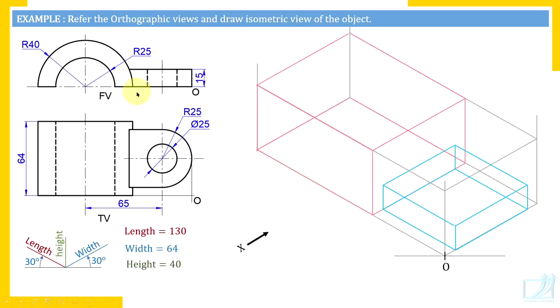Now watch here. We'll have to locate the center. So center is along the base at distance 40 millimeters from left end. Remember your focus is on this front surface. This front surface has semicircular edges and not straight edges. So this semicircular edge now we are going to draw. So we are using 4 center method. First of all, you will have to locate the center of the semicircle. So it is 40 millimeter from left, and draw these center lines.